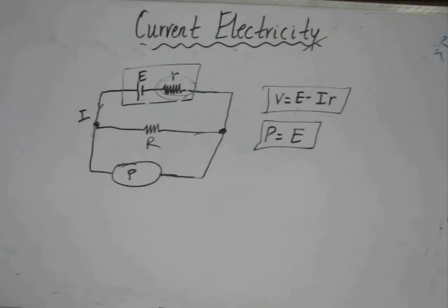The other advantage is that a voltmeter is not as sensitive. It can't measure very small EMFs, whereas a potentiometer can be used to measure the very small EMF of cells. We can also increase the sensitivity or accuracy of a potentiometer by increasing the length of the potentiometer wire. That means we can measure an EMF which is very small.